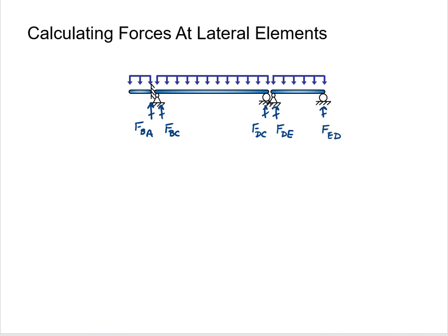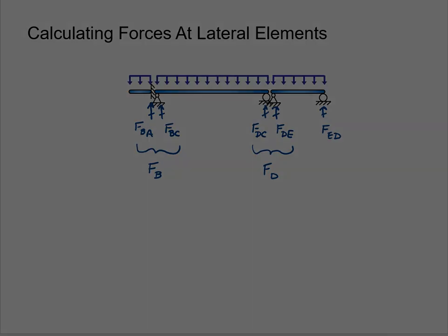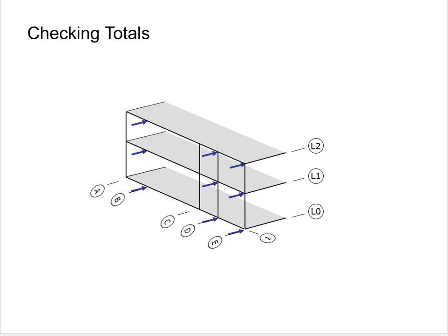Note that some lateral elements get loading from panels on two sides, so we add the reactions calculated from the left and right to obtain the net force on the lateral element. Performing this analysis at each diaphragm level gives us the point forces at all levels of the lateral elements.